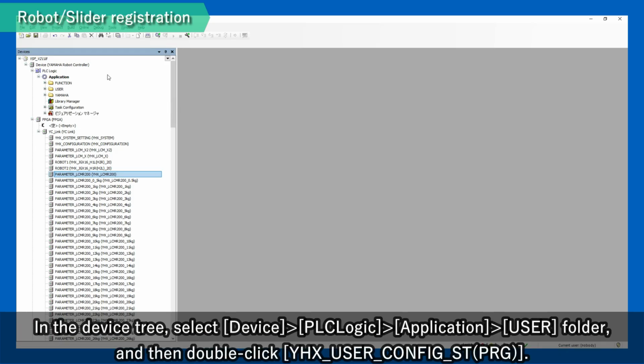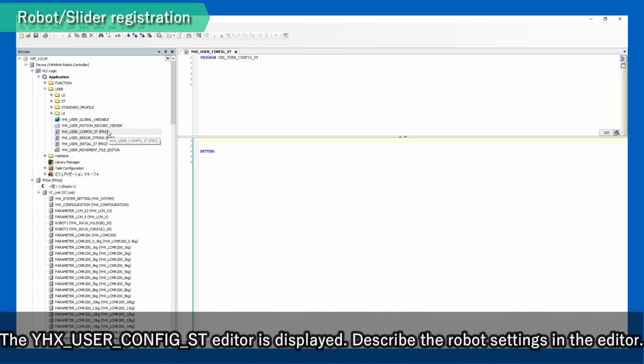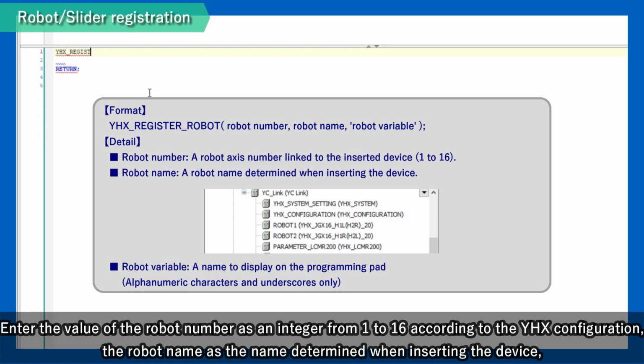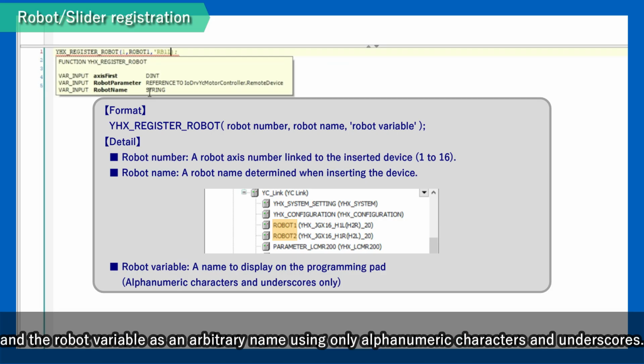In the device tree, select Device, PLC Logic, Application, User folder, and then double-click YHX User Config ST. The YHX User Config ST editor is displayed. Describe the robot settings in the editor. Enter the value of the robot number as an integer from 1 to 16 according to the YHX configuration. The robot name is the name determined when inserting the device, and the robot variable is an arbitrary name using only alphanumeric characters and underscores.